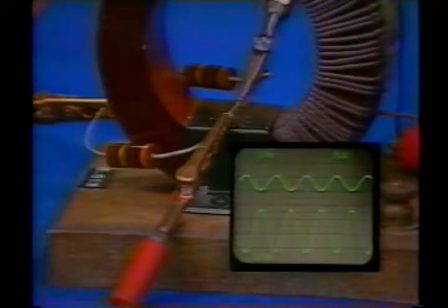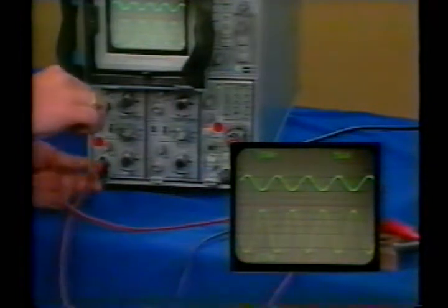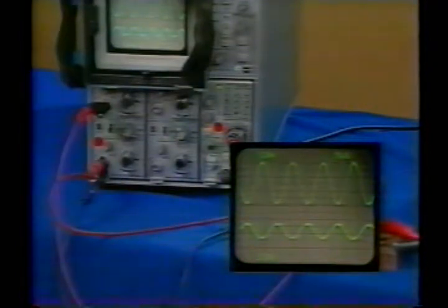Faraday's integral law accounts for this seeming failure of Kirchhoff's voltage law, for how it is that different voltages are measured by probes connected between the same nodes. This is a cross-section of the core. The pair of resistors are connected in series. The node that is connected to the ground terminal of each probe is here. One scope terminal is connected to the other node like this, while the other is connected like this.